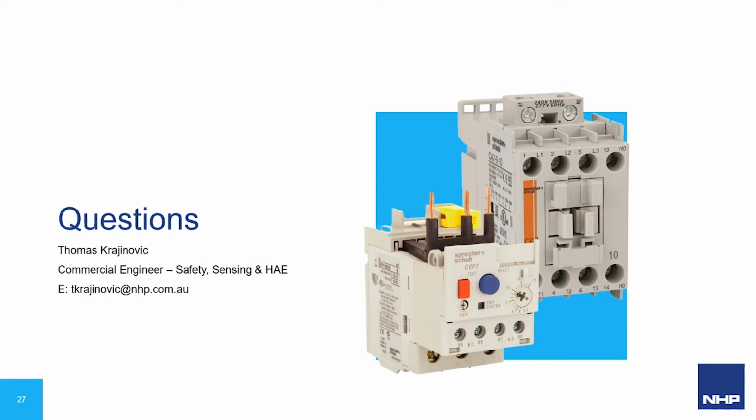Now, just another important thing to note is that it's actually the responsibility of the motor manufacturer to type test soft starters and drives with their motors. So this would effectively mean that you would need to approach the motor manufacturer to determine what model drives are suitable with their motors. And you just have to look at the hazardous area certificate. Now, if you are really set on using a particular drive and it hasn't been type tested, and you don't want to use temperature monitoring, there are actually test labs out there that do type testing for you with the motor that you're looking at and your drive or soft starter. So if you really want, you could approach them as well.